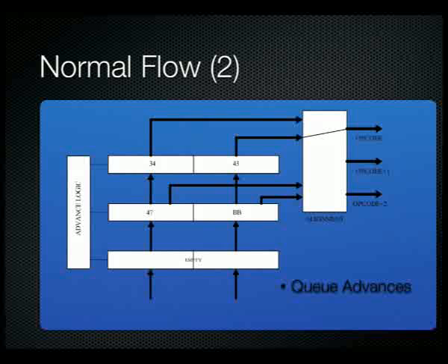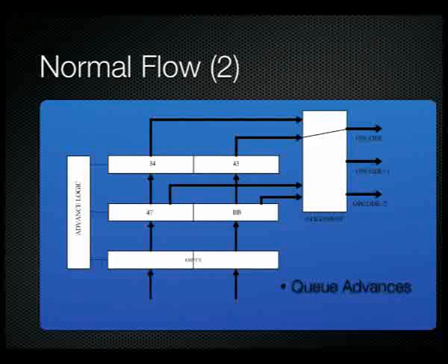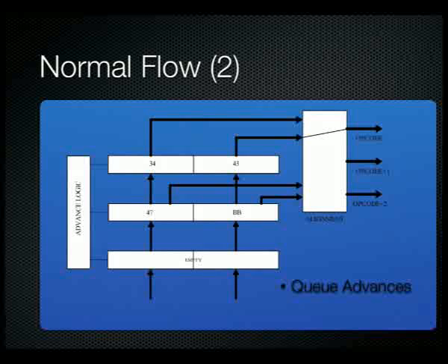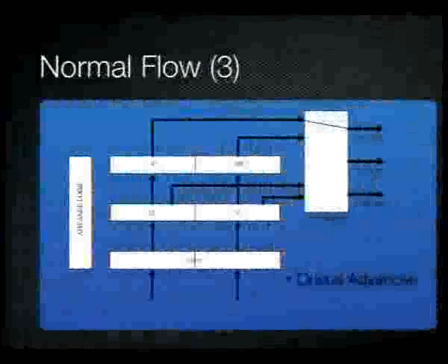Okay, so we have 43. It's only a single value for that instruction. It's what we refer to as an inherent instruction. It has no operand, so therefore 43 is latched through. Of course, the next 2 values would be latched through, but the instruction decoder would just ignore them anyway. So the whole queue advanced up by 1 stage.